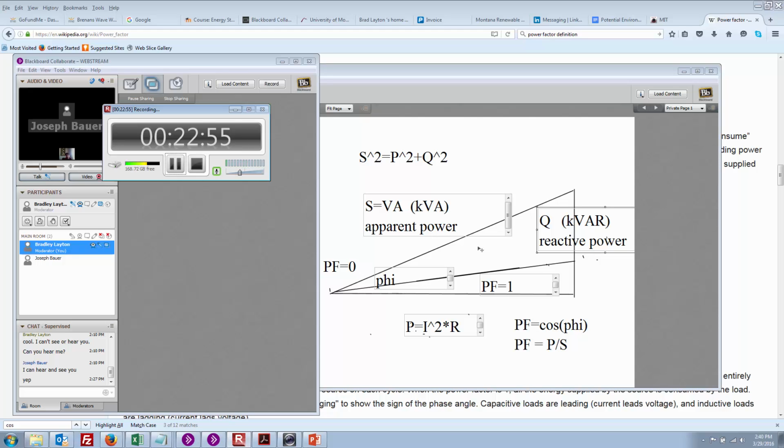And really from here, once you understand the math and the physics behind it, it just becomes a financial issue. And we spent week 2 talking about finances. So there are some subtleties, but it's basically just looking at how much reactive power you might have had over a given period of time, and then the utility has a certain charge for that. So once you understand the physics and can measure what these kVA and kVARs are, and in fact you can,